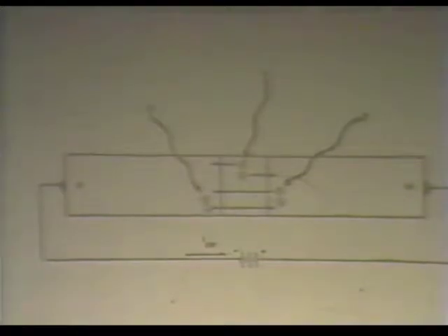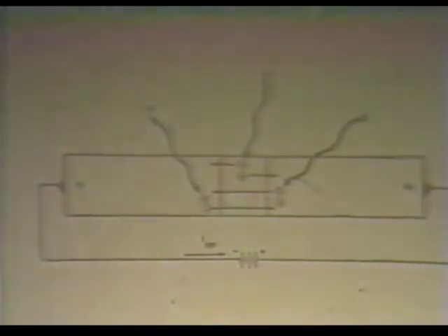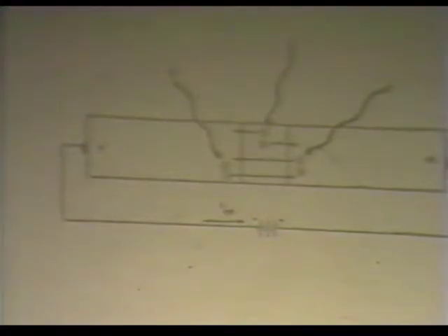Sometimes, in the case of MOS devices, which we're going to get to, you may generate a voltage spike somehow big enough to punch through your oxide too. That's especially a weakness of devices called VMOS devices. When you get in high dose rates, they'll punch through the sidewall. Okay, so you're creating photocurrent, which is nothing more than radiation-induced free carriers that make that device behave like you don't want it to.